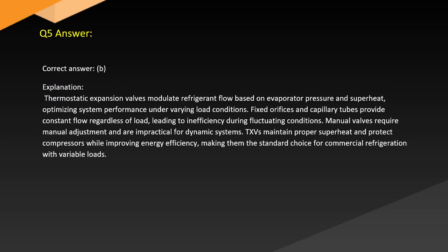Answer. Correct answer: B. Explanation. Thermostatic expansion valves modulate refrigerant flow based on evaporator pressure and superheat, optimizing system performance under varying load conditions.